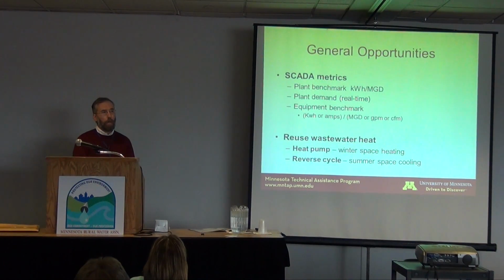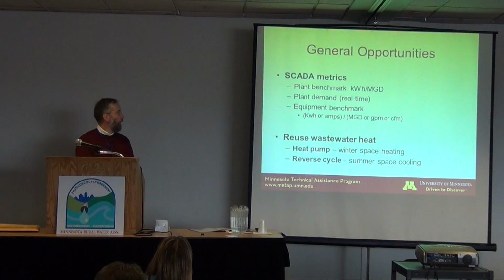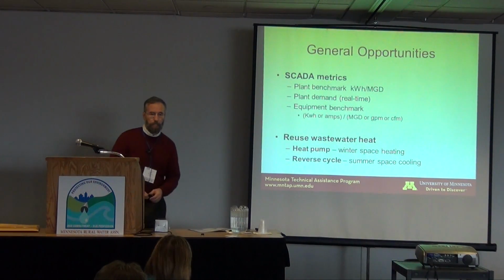I think there's also a lot of possibilities with SCADA systems to benchmark individual pieces of equipment that are important. Blowers would be an example, where you're measuring in many cases amps, and many of the plants have airflow measurements. Have the SCADA system combine those to give you a real-time measure of what is the air generation efficiency. And I guess we'll go to the next.